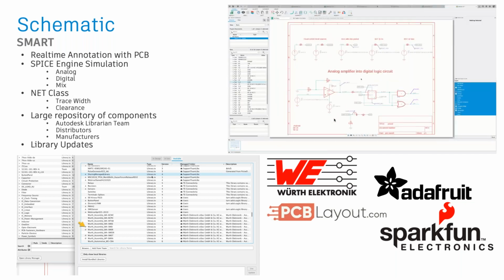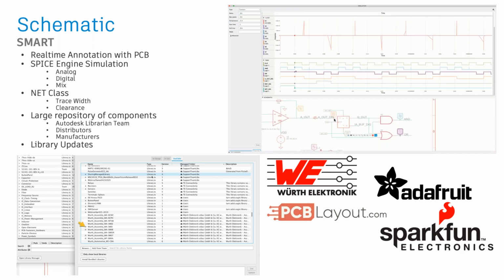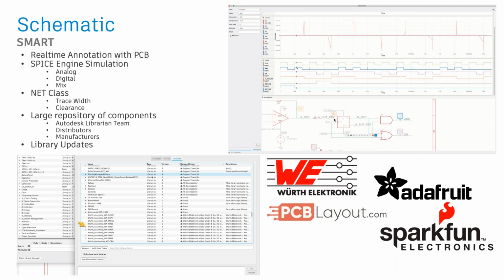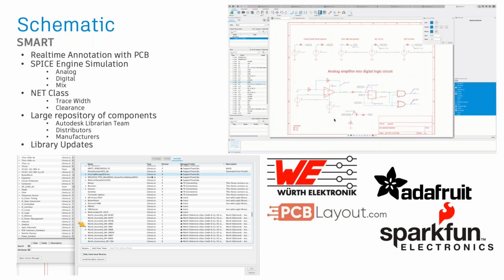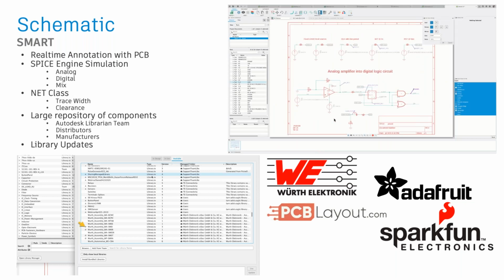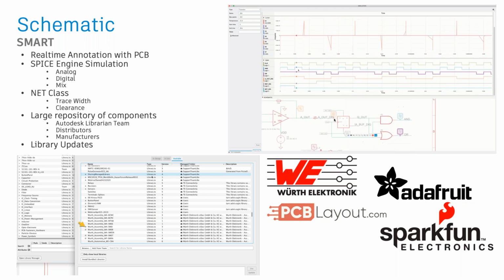Now, the connections defined on the schematic may have characteristics that need special requirements. Let's say, for example, there's a line on a schematic that's going to have a heavy load. Therefore, that line needs to be thicker than our conventional lines for digital connections. With net classes, we're able to specify and give special characteristics to our connections in the schematic, which are going to be obeyed by the design rule checker on the circuit board. That's referred to as net classes.